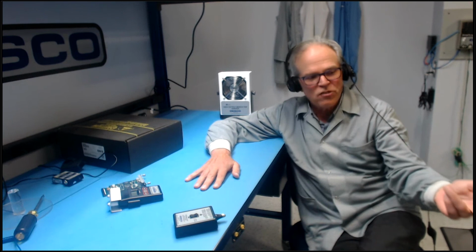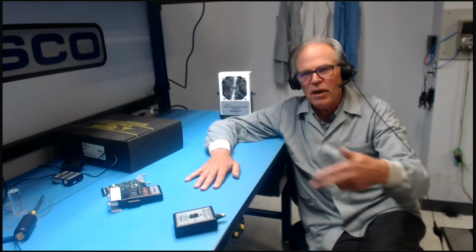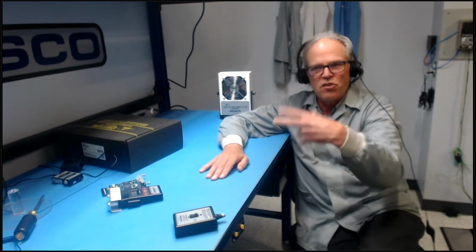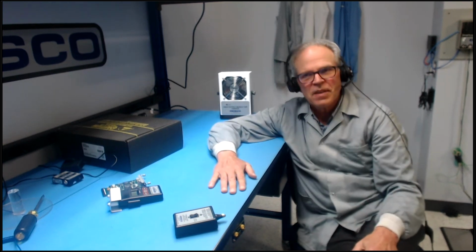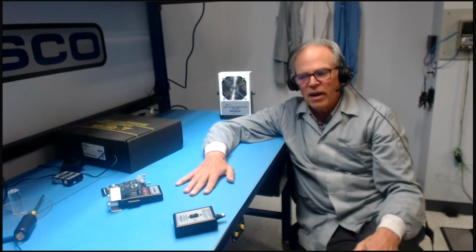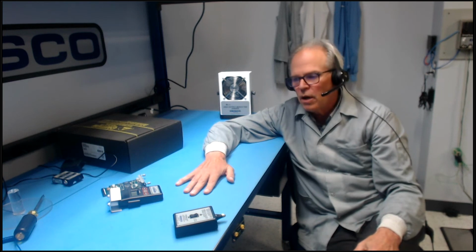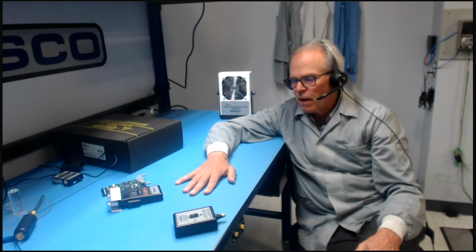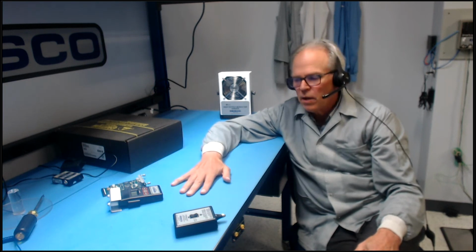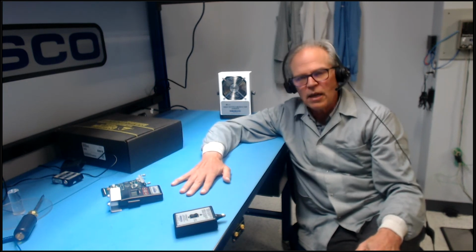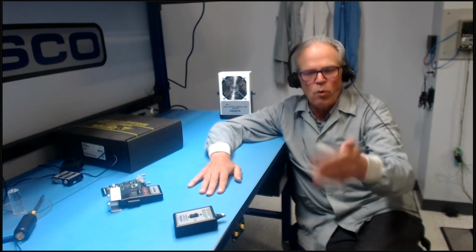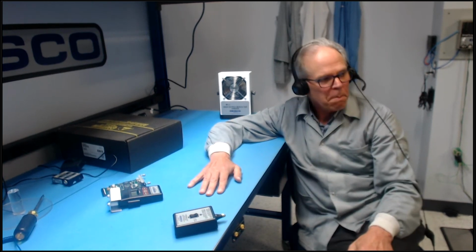So we ask the customer for a Q-tip and some IPA, reach inside and clean a couple of emitter points, turn it on, and it's good as new. So it's about getting a baseline for the performance of the ionizer, and then cleaning it with IPA and a Q-tip on some scheduled basis, even if it's performing well, just to prevent it from corroding.